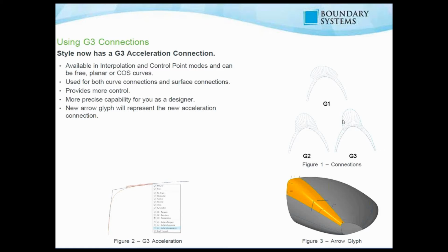So each added edge will break the 4-sided face into smaller faces, providing enhanced control, as we see there in Figure 1. So what we can also do, as we see in Figure 2, is delete those edges to further refine our control. So in Creo Parametric, we'll automatically delete vertices that are no longer needed after the edges have been removed.